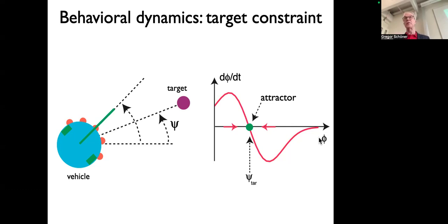So angular variables have to have periodic solutions. If you don't do periodic, somewhere there will be the transition from 0 to 360, and the dynamics is supposed to go smoothly through that because it's the same point. So a linear function would make a jump there, right? We don't want that. So we'll use sinusoidal functions, or sine and cosine functions and so on. So in practice, this contribution will very typically be a sine function, actually a minus sine